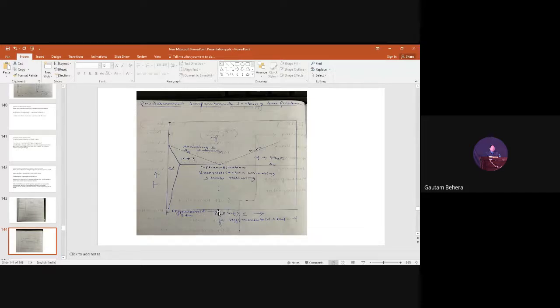And you have to remember, if I have a hypereutectoid steel, for normalizing I have to go above ACM. But if I have a hypereutectoid steel and I want to do full annealing, I do not have to go above ACM. I have to remain in this temperature range: above A1 but below ACM, or in between, you can say. Why, I will tell you in the coming class.